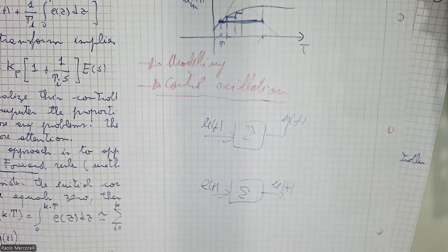But of course, if the model plays a role in the controller, model predictive control must be considered in discrete form because it's part of the controller. It's important to analyze this in terms of the controller because in MATLAB, everything which we have here is not analog, it's discrete.